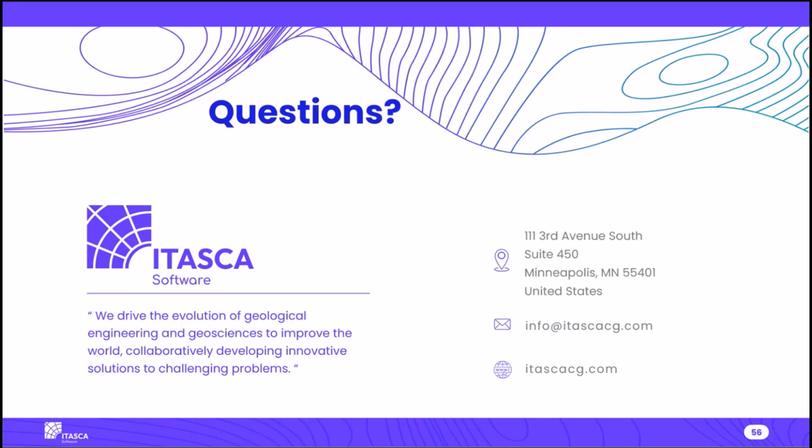Yeah, and one of the features I like about Maxwell damping is that I've had so many endless discussions and debates about what exactly the center frequency you should use for Rayleigh damping is, because you have such a narrow frequency range of constant damping. With Rayleigh damping, you really do need to know what frequency your structures have. With Maxwell damping, it's much less important to know exactly what frequencies you'll have. But of course, you should have some idea. And it's not just the frequencies of your actual structure, but also the frequency content of your input motions that you need to take into account.